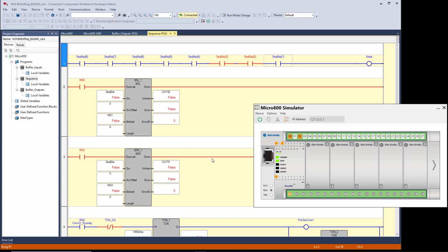And remember, if you unload a 0, that doesn't turn on output 1. So let's shift our bit shift right one more time, and you see output 1 is on. Down here, output 1. Shift it again, output 1 is still on, shift it again, and it's off. We've shifted out all the ones. So that's simple.